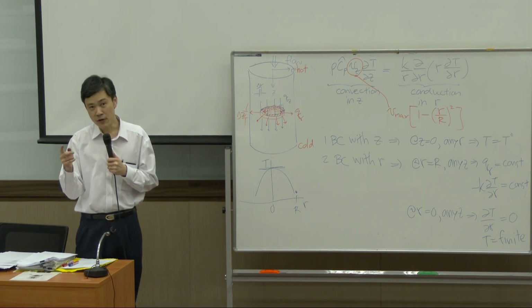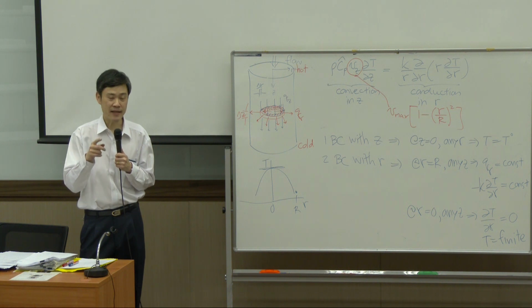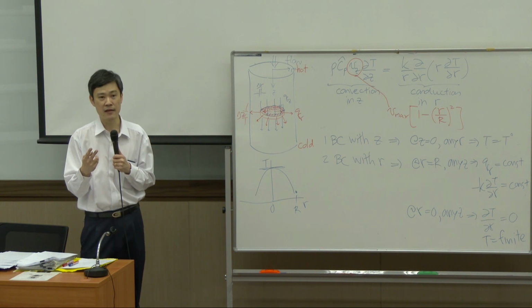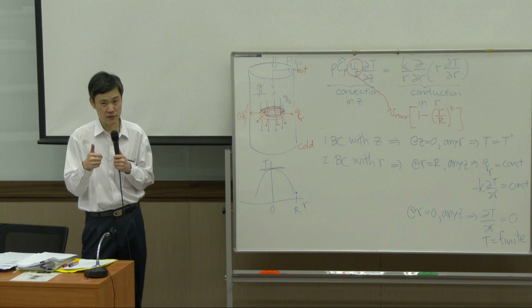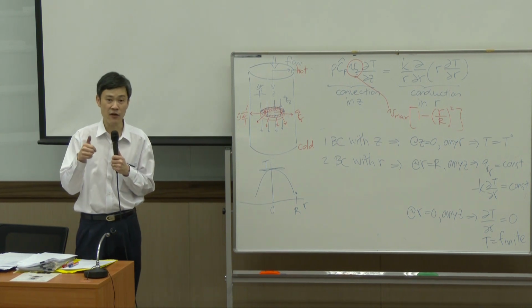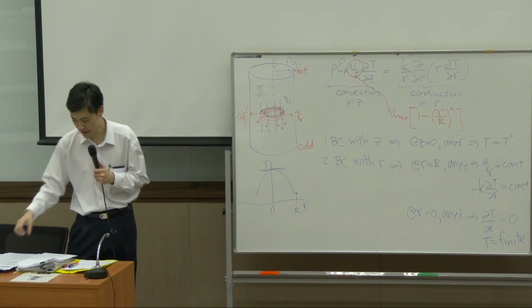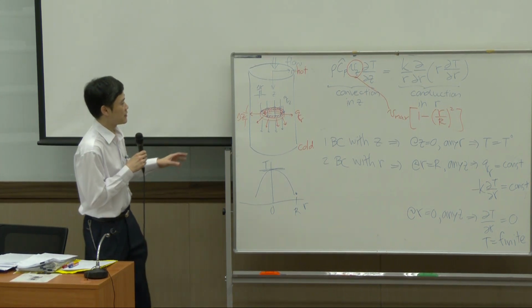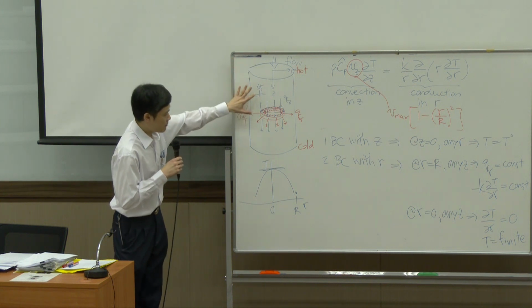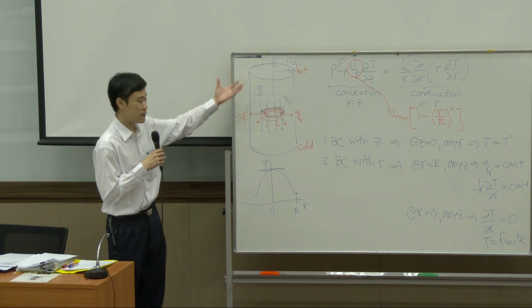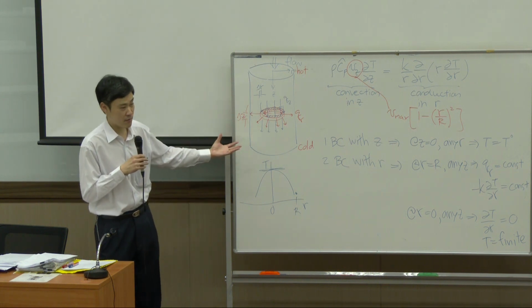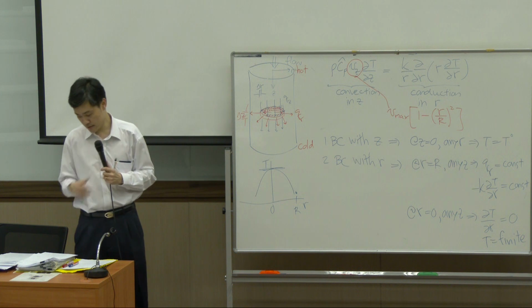The fourth example is natural convection. In that case, we still have both energy transport and momentum transport. But in that case, we have to deal with energy balance first because density is a function of temperature. And then comes forced convection. The problem must deal with momentum first because convection is more important and we need the velocity profile to calculate the convection part. And that will be the rest.